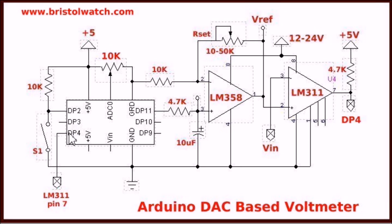What did this do? Okay, digital pin 11 was set up in order to utilize its pulse width modulation output, which through this filter gave us a voltage from 0 to about 5 volts. This LM358 is used as a voltage amplifier, not a comparator, which feeds to the plus input of the LM311.